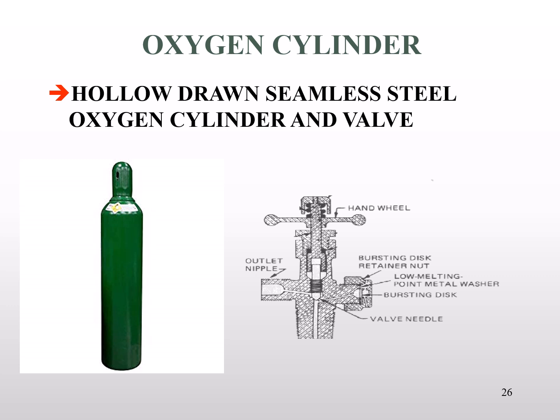To start with, these valves are made of brass. The reason brass is used is brass will not create a spark if it's hit by other types of metals. So it's spark resistant, making it safer. Now that does leave the valves being softer than many other metals. So therefore we have to be careful when the safety cap is off the cylinder, because it's conceivable that we could break a valve off, turning that oxygen cylinder into an unguided missile. Another safety feature built in is there's a burst disc located opposite of your supply side.